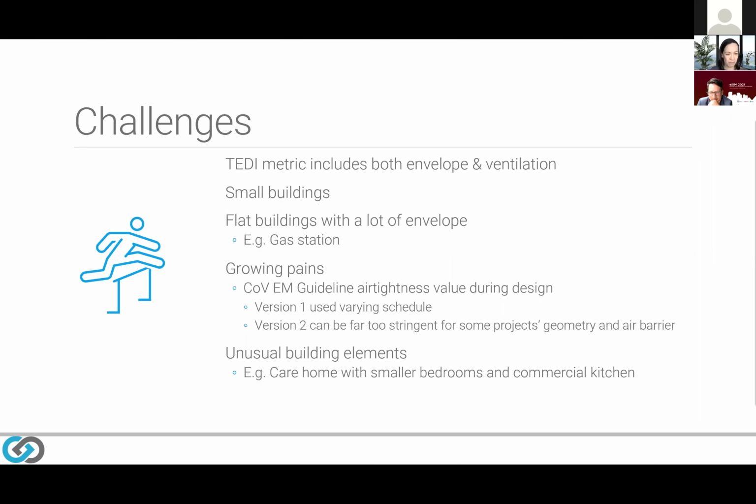Another area that has been a challenge is small buildings. Of course, when you talk about an EUI target or an intensity target, smaller buildings with their smaller footprint get a much smaller energy budget. And arguably, they are more efficient because they're smaller. They're using less land, less materials, etc. The step code adapted to adjust some of the requirements. I showed you the Part 9 calculation, how the heating degree day gets linearly interpolated.